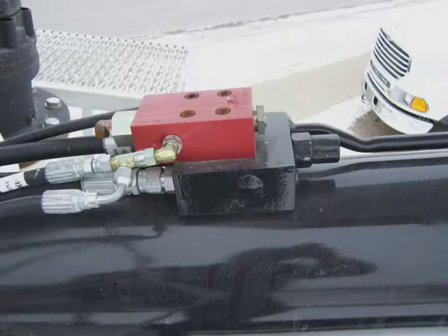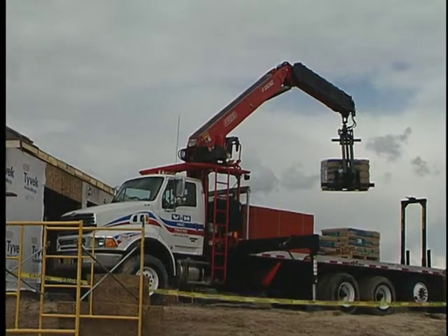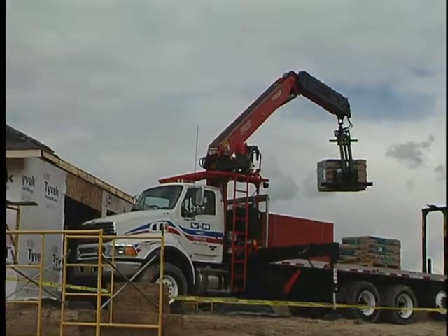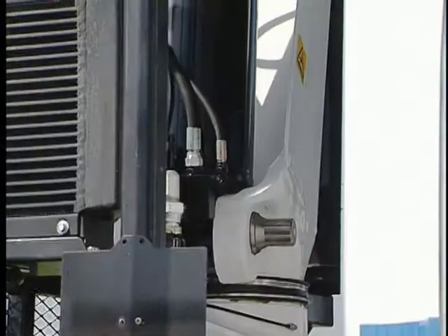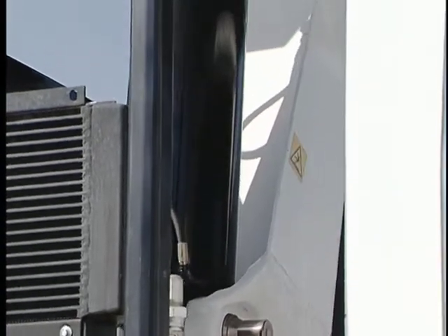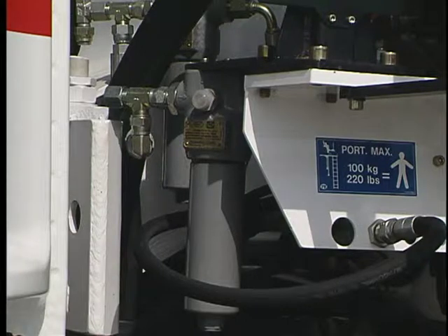Integral mounted holding valves prevent sudden cylinder collapse in the event of hose failure, prevent crane overload, and stop uncontrolled boom drift. Rack and pinion rotation on the model shown features minimum rotation of 400 degrees and provides precise control and positioning. The high-pressure filter system is standard on the model shown.